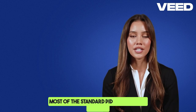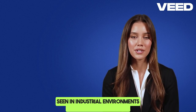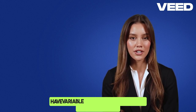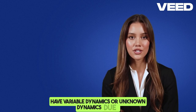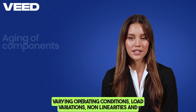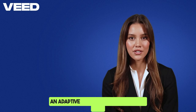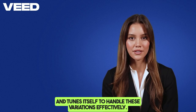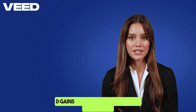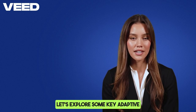Most of the standard PID controllers we have seen in industrial environments work well for systems with fixed dynamics, but real-world systems often have variable dynamics or unknown dynamics due to varying operating conditions, load variations, nonlinearities, and aging of components. An adaptive PID controller is the key here and tunes itself to handle these variations effectively. Adaptive PID controllers continuously modify their P, I, and D gains based on real-time flight conditions. Let's explore some key adaptive techniques used in aircraft control.